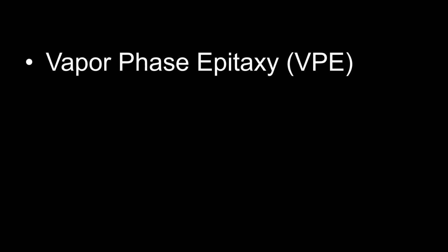One of the most common techniques used in chemical vapor deposition is known as vapor phase epitaxy. Basically, as I previously discussed, the precursor molecule is converted into a vapor phase, and then the vapor phase is deposited on the surface of the substrate as an epitaxial thin film. So this is also a very important type of chemical vapor deposition process. I have already discussed combustion CVD, so I don't need to discuss it here.